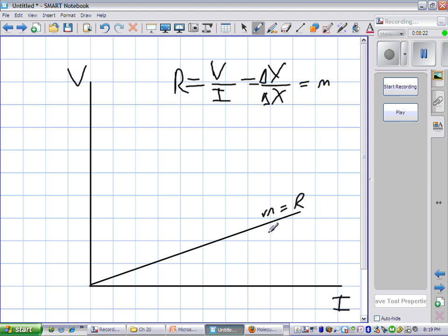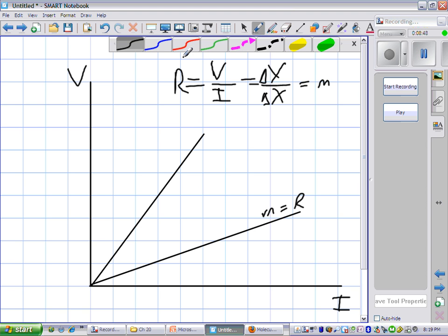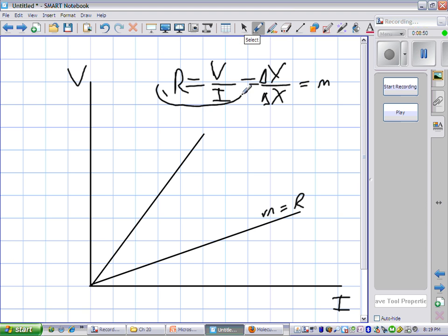And so you'll see that this resistance is not quite as big as this particular resistance. So you draw another circuit, and you'll have a bigger resistor in that circuit because the slope is larger. You'll see voltage here, and you come across and you'll find the current, so a high voltage will be a higher current, low voltage will be a lower current, and that follows this relationship of Ohm's law here. R equals V over I. And that's how the graph works. The slope equals the resistance.